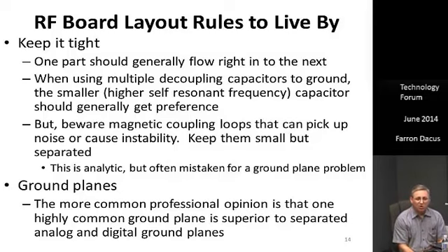But in RF here, we're looking for stuff that's perfectly isolated. So you might be surprised that, for example, you have a switching power supply, and you bring it near some sensitive circuitry. Then you put a linear regulator. And on the other side of that linear regulator, you have your sensitive circuitry. So there is a loop parallel to the ground plane where current flows, a current loop. And then over on the output side of the linear, there's another current loop.